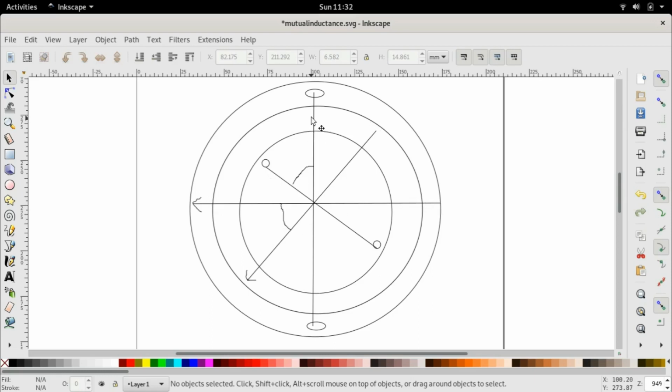The reason is, in exactly the same way as we did in the previous lecture, we must ask this question: what will be the projection of this rotor flux on this stator flux? Because this projection would be the actual flux that is linking with the stator. So, as always, it is quite obvious that this rotor flux multiplied by cos of this rotor position angle theta m is the flux which links with the stator.